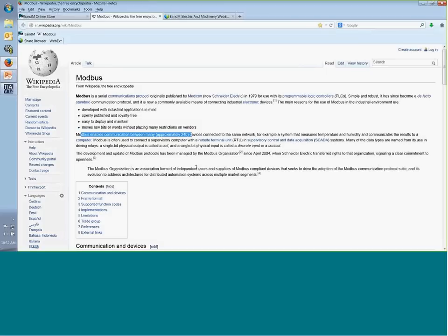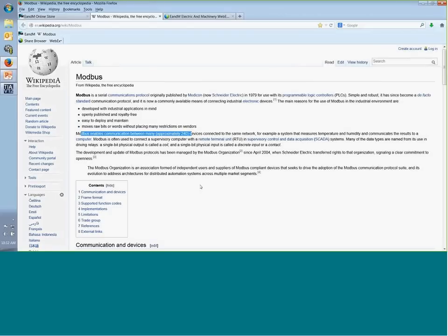But Modbus serial communication is kind of slow, usually around a 32K baud rate. So if you have a few hundred devices connected, it will be polling data from each device one by one, and it just takes time. So the update rate will be a few seconds.